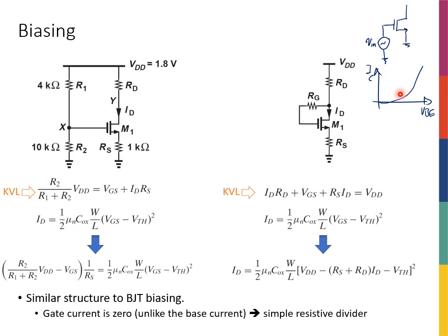If the base emitter voltage is in the order of like 0 volts or a few millivolts or even a couple of hundreds of millivolts, the slope is actually pretty small. The curve is still pretty flat, and if I want to get a good gain, I have to be somewhere around here, and we found out that means somewhere around 0.7, 0.8 volts, okay?